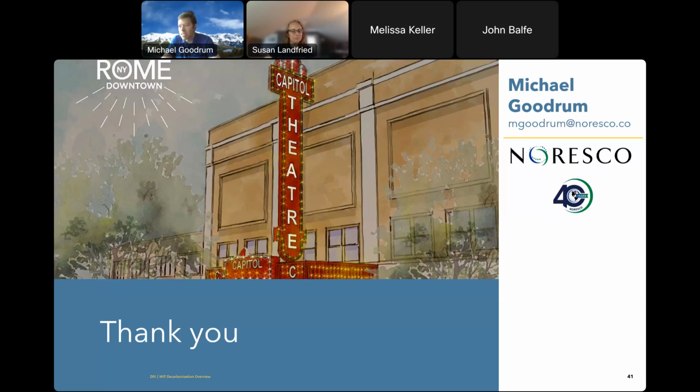I remember seeing an old church in, I think, San Francisco, and they had the luxury of time, so they had collected data for a year or so. They basically found that because of the masonry, stone structure, it kept a pretty stable temperature, and in many of the seasons they could shut off the HVAC and just let the building keep its own temperature.